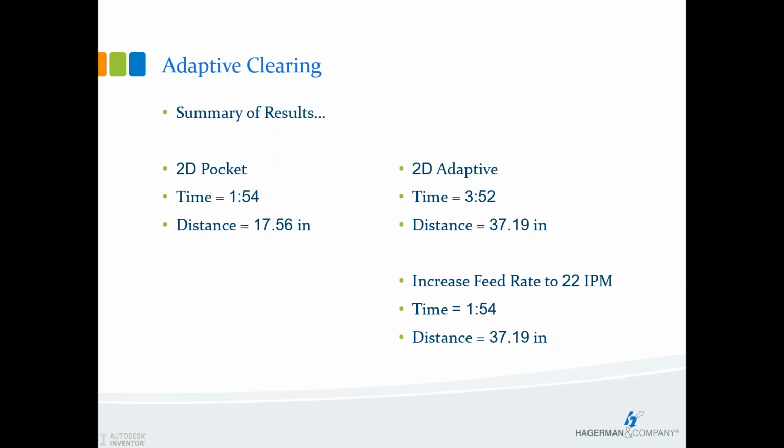My personal opinion, if it's a perfectly square pocket or perfectly round pocket, it's kind of a wash. When you start getting into unique shapes where you might be burying the tool, I think I'm going to go the adaptive approach, even though it may have a slightly longer runtime.